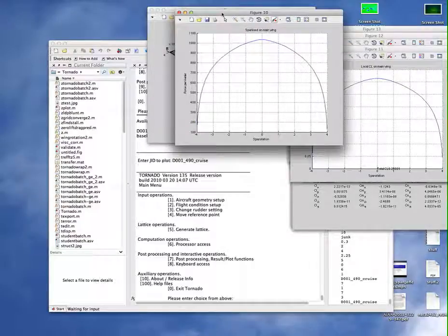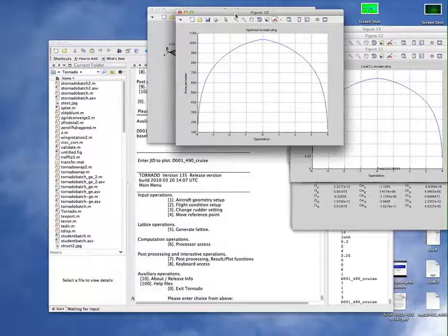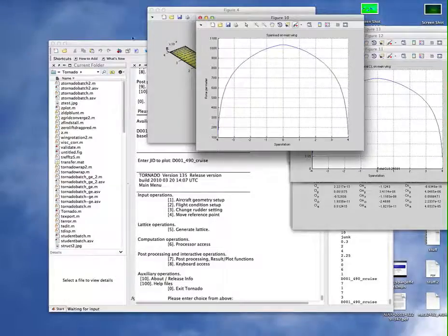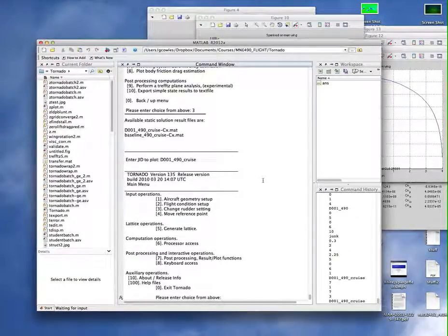Twist can also be useful to make sure that not just we have the lowest induced drag, but also we can ensure, for example, that we have stall occurring on the roots before the tips. So our tips maintain control even in stall conditions. We're not considering that in your design project. Your goal is least amount of drag.